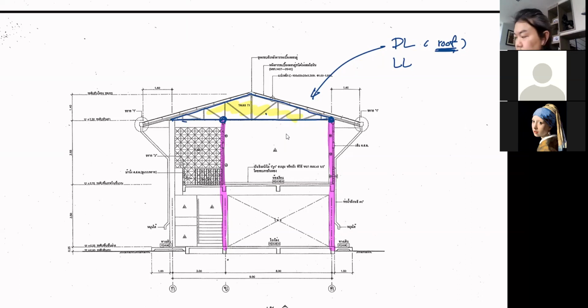So after you select the roof, you will know the weight, the load, and you will know the spacing. When you know the spacing of the purlins that you need to support your tiles, now you know how you can select your truss configuration, because generally your purlins should sit on top of each joint.